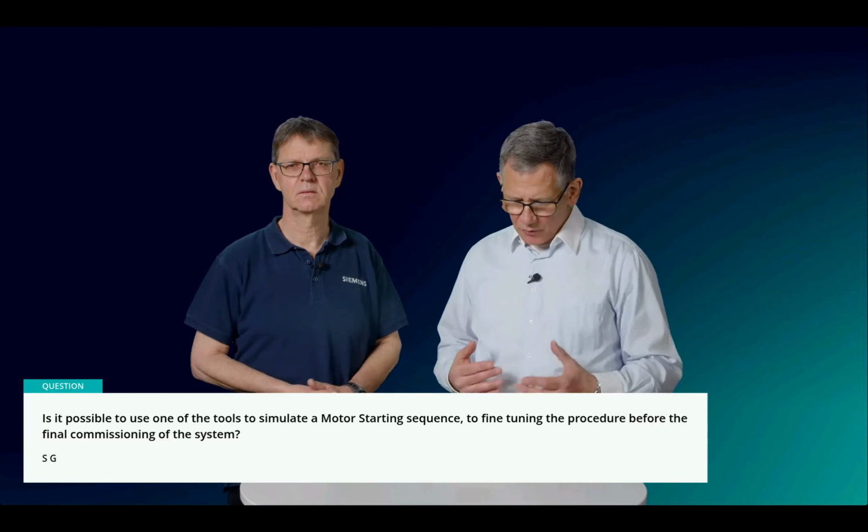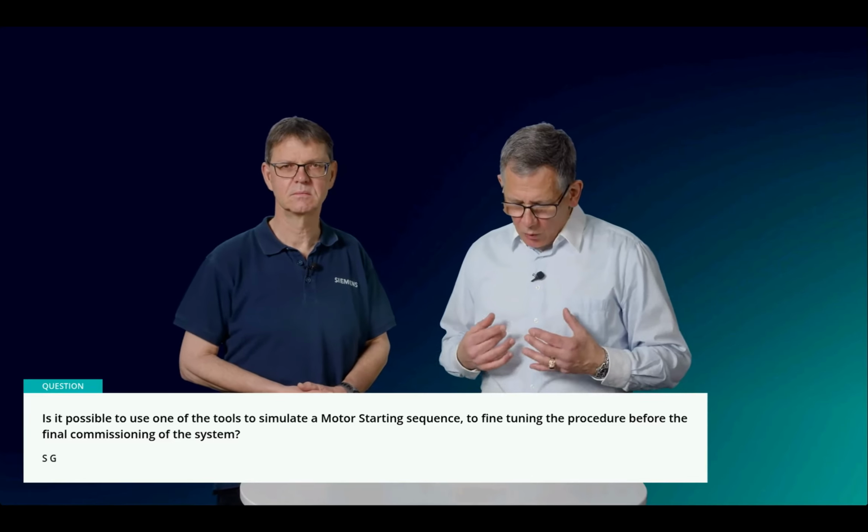Another question that we received from several sources. What would be the rating of a motor to have the requirement for 87M or for differential protection, and when is regular overcurrent protection enough? Yeah, this is not so directly to be answered. It depends on how critical, how important the motor is, and how much money at the end someone would spend for the protection of this motor.